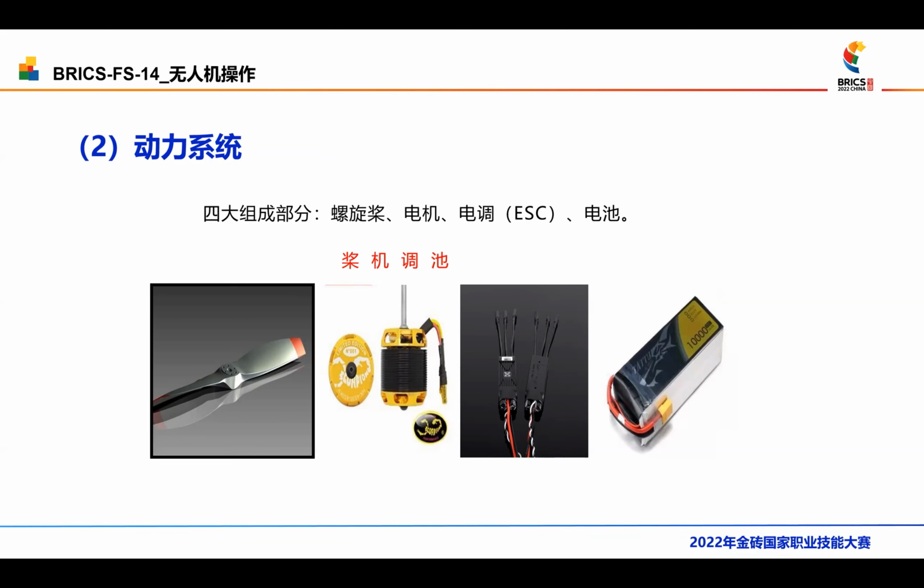Generally speaking, if the first 2 digits are greater than 40, they need to be divided by 10. The last 2 digits must be divided by 10 under any circumstances, such as DJI 8040. Here the unit of the propeller is inch. 1 inch equals 2.54 centimeters.